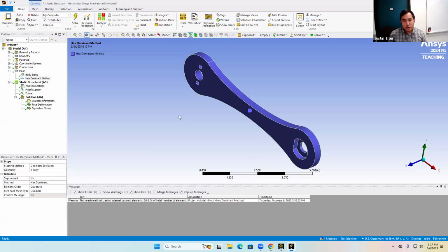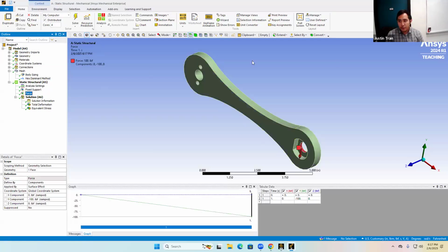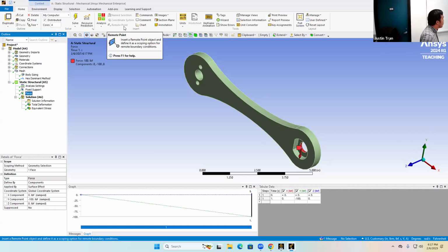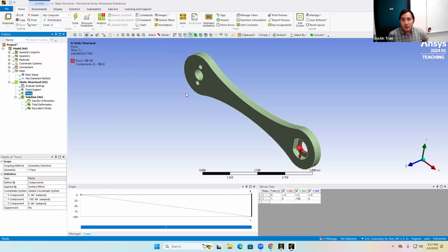Okay, so I know it's not 6:20 yet, but it feels like everyone's gone down this part. So I hope you tried out a couple of different directions of the force. The direction of force that actually creates the most stress here is a force in the y direction, either negative or positive y. The reason is that if you put a force in the y direction, you're basically putting this beam into bending.